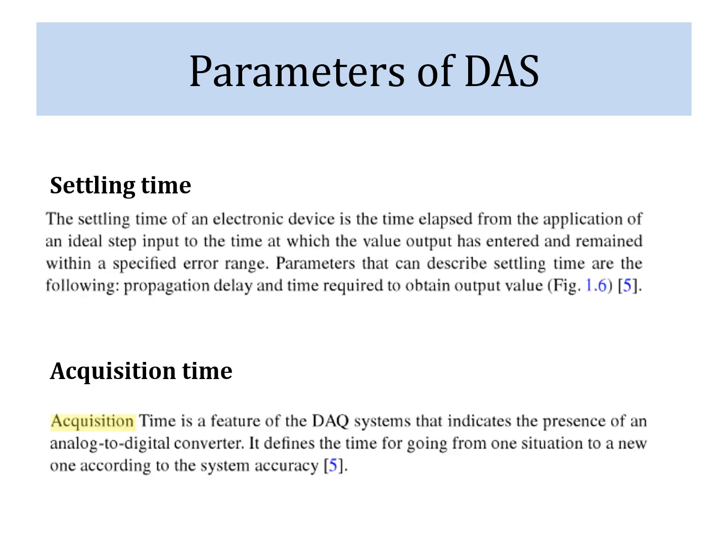Next parameter is settling time. As we know, when the data acquisition system starts acquiring the data, there is some transition, and after that transition the system output gets settled down. So, whenever that output gets settled down within plus minus 10% or plus minus 5%, there are different ranges for the definition, or plus minus 2%, but usually we take plus minus 5% of the final value.